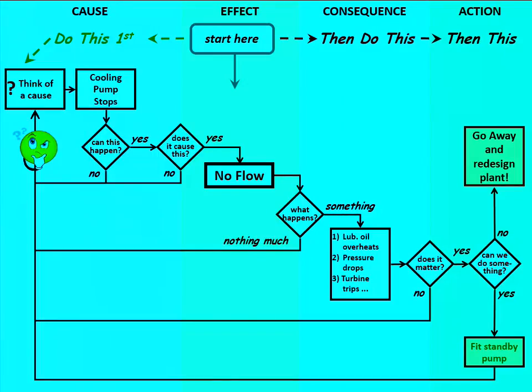Because occasionally you will say, no, we can't. That can happen. You say, we can't do anything about this. There's no feasible solution to this. In which case, you've identified a hazard and you can't fix it. So you have to be prepared to go away and redesign your plant if necessary. Fortunately, most of us can sit around and say, yeah, sure, fit a standby pump. That's something we can do in this case. So if you go through that, you're asking yourself the right questions at the right time, and that will take you through it step by step.